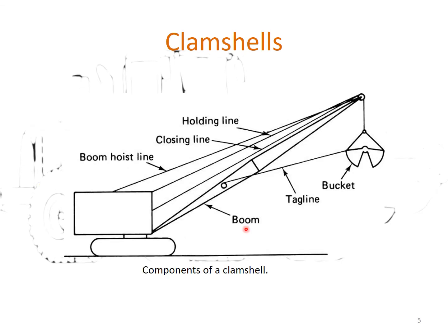And the next one is the clamshell. For the clamshell, why we call it that, because of the clamshell bucket, as you can see here, and it also uses cable, so it is similar to the dragline. It will be versatile, difficult to control, but because the boom is high, you can lower down this clamshell, so it means that you can excavate in a deep pit, at a very low level. For example, if you do a shaft, which is normally used in trenchless technology that I'm going to present in the next few slides, you can use a clamshell to dig vertically, can be 100 feet below the grade.